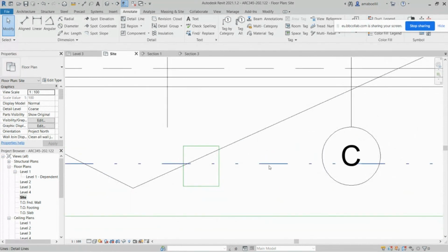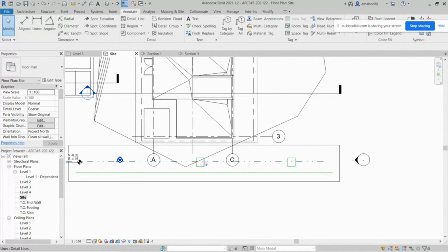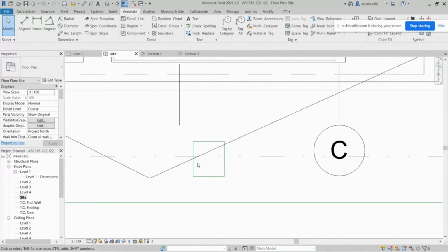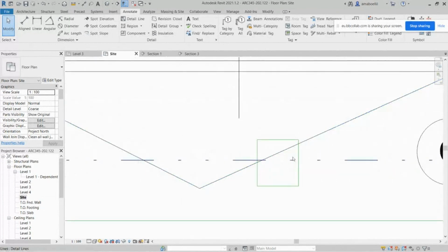The sewer system needs that, of course, because the pipes will start and end here and start again there, and then we'll have a point where the water will come inside and then get outside. If the slope is going in this direction, the water will flow in this direction, come into that manhole, and then come outside from this. So this is a checking point. It's needed, because if any problem happens, you cannot demolish a portion of the street here. You have to just get inside here and check whether there's a problem or not.